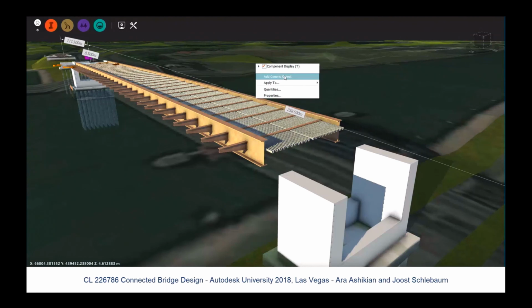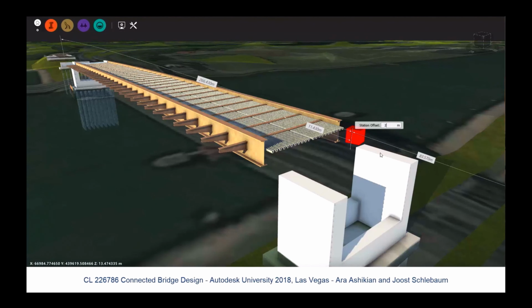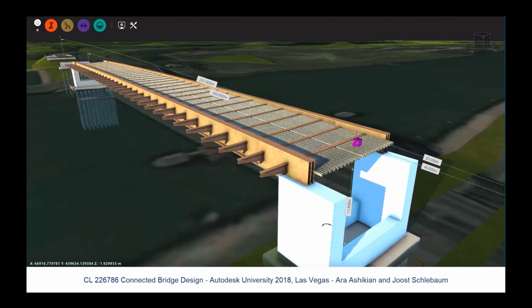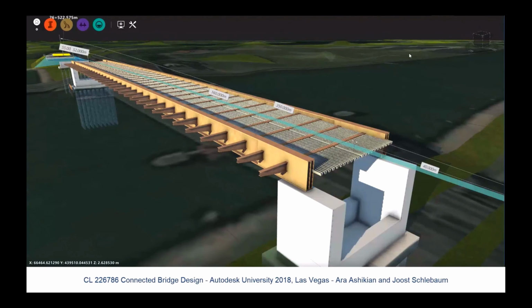It's a good combination of flexibility. Now I'm going to select the other end. I'm just going to reuse all the parameters I already set and bring them over here. So in the workflow, we make it convenient: you inherit geometry or parametrics from one part of the bridge and bring it elsewhere. I'm adjusting the pier because of the vertical profile. I lowered the dimensions there.